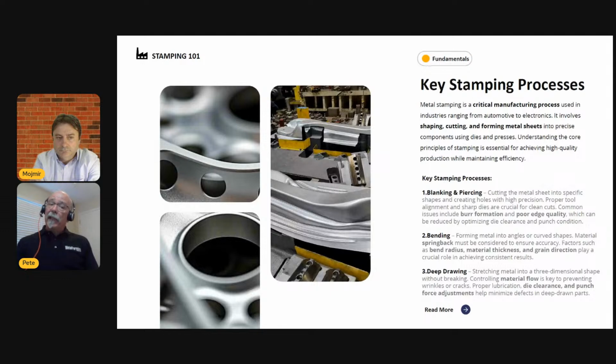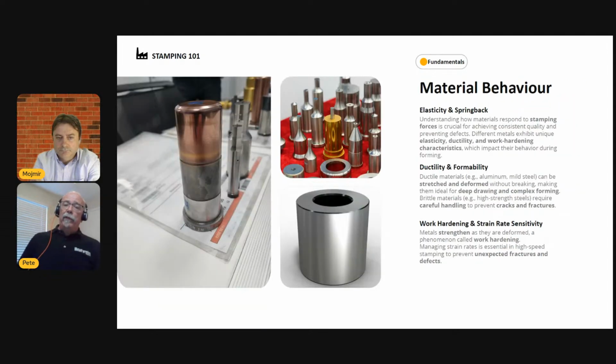So if that sheet metal is getting 40% thicker in the flange, when it bends over the die entry radius, if there's no clearance for the material to get in there, that's what causes the sidewalls to stretch and eventually fail. So a very important parameter that we have to keep into consideration.